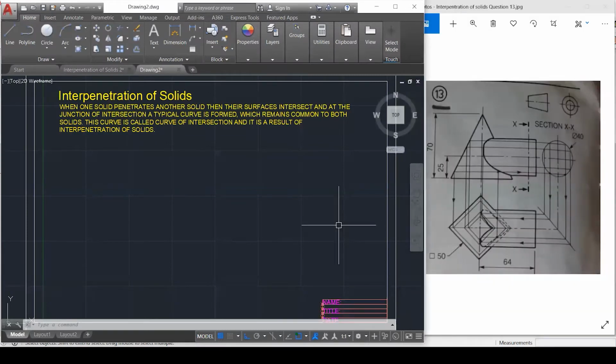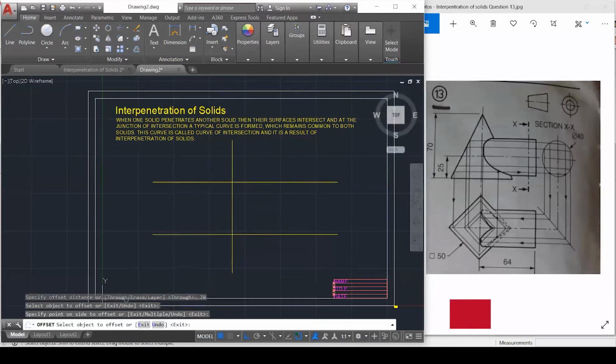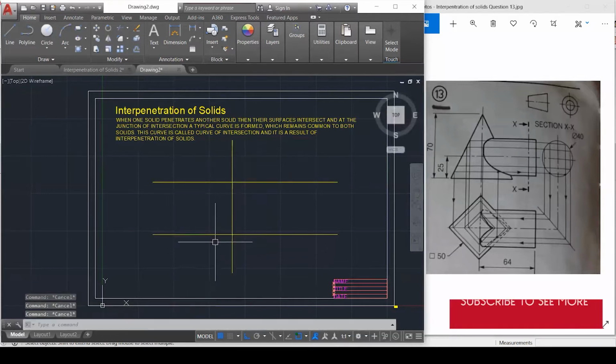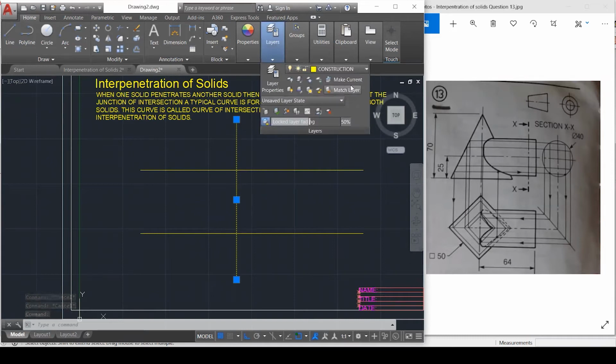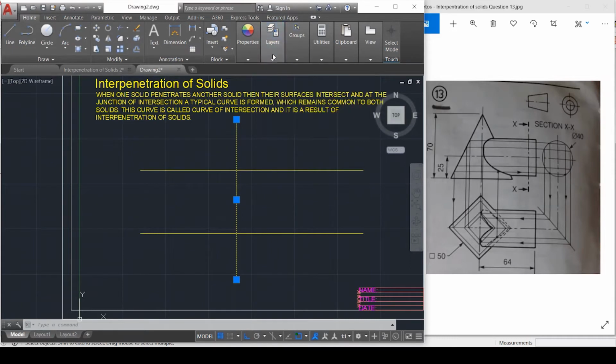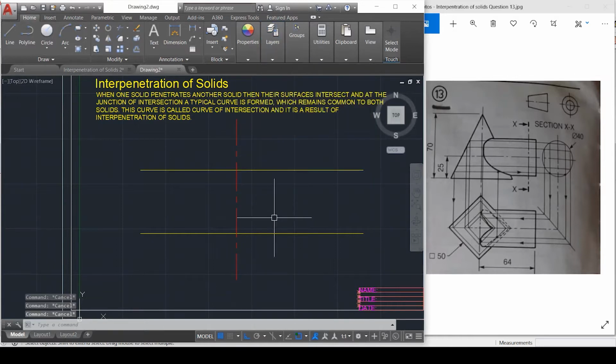All right, so let's start drawing this. What do we know? We know that the height is 70. So the height of this is 70 millimeters, and it goes up. I'm going to use this as my center line, and insert that into my center there. And we know that the square at the bottom is 50 millimeters. So let's create that square now at the bottom.